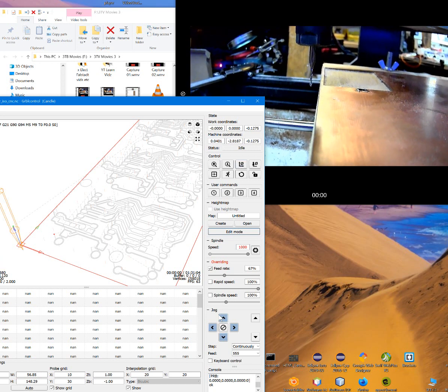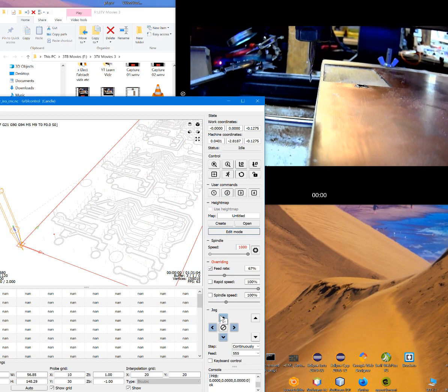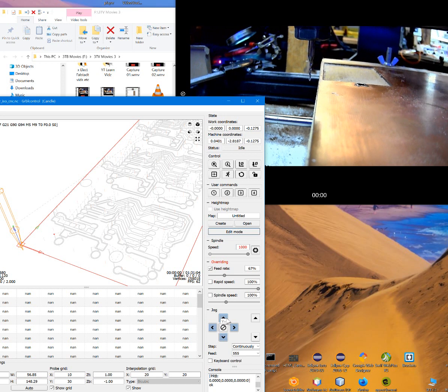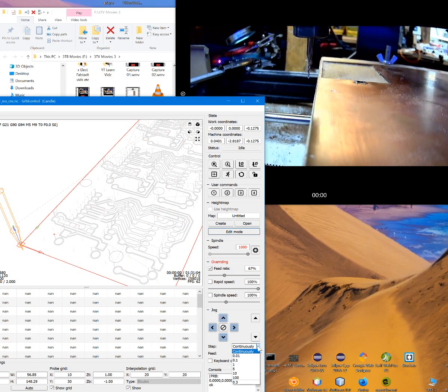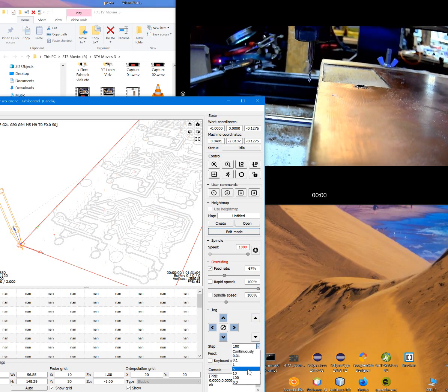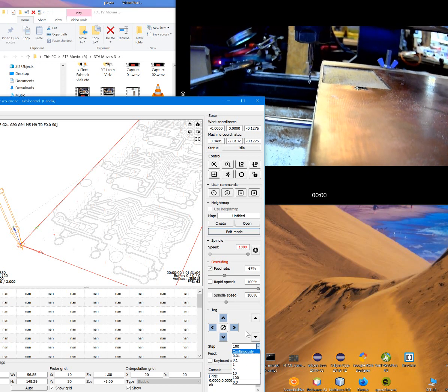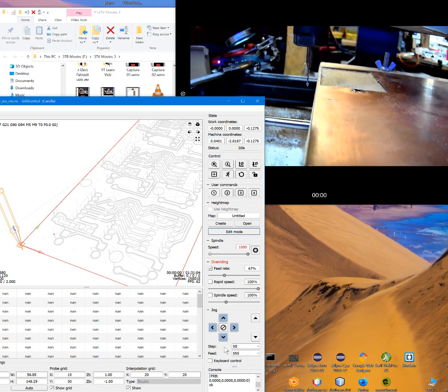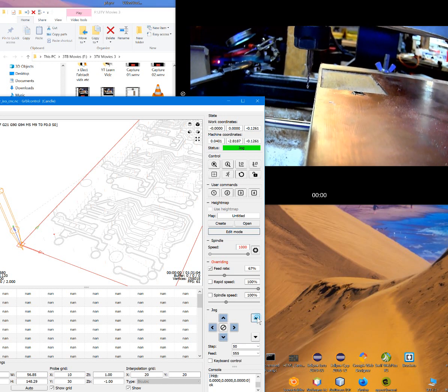All right. And then I want to make sure, because we said our tool on this is 100 mil, right? Okay, and then it's got to go into 150 mil, so let me go ahead and instead of making this continuous, I'll make it like 100 mil. Well, no, I'll make it 50 mil. Type that in. Okay, so I got it set to 50 mil, and this is the absolute limit.